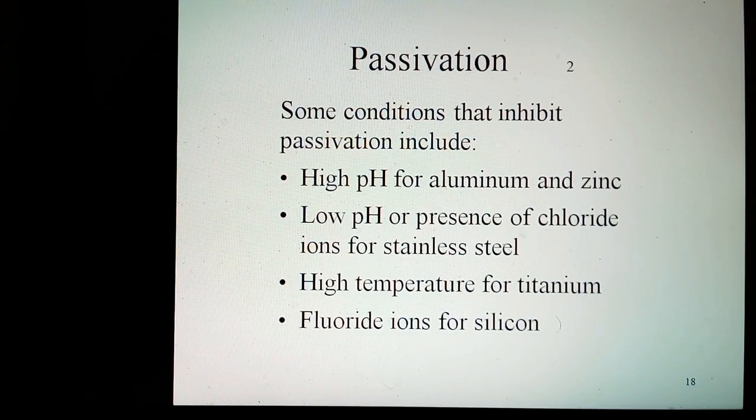Some conditions that inhibit passivation include high pH for aluminum and zinc, low pH or the presence of chloride ions for stainless steel, high temperature for titanium, in which case the oxide dissolves into the metal rather than the electrolyte, and fluoride ions for silicon.